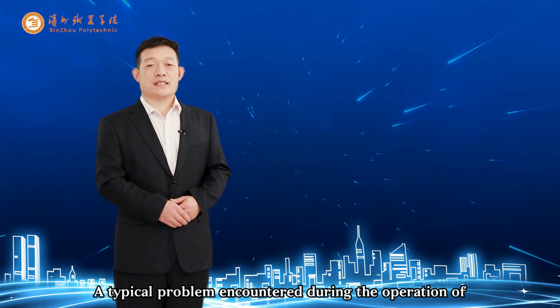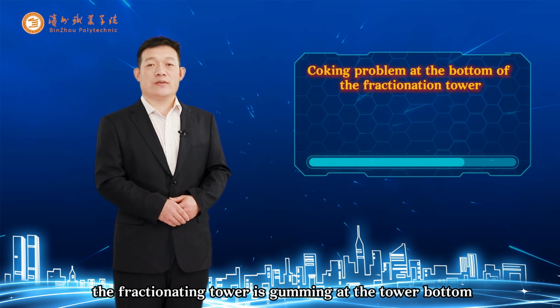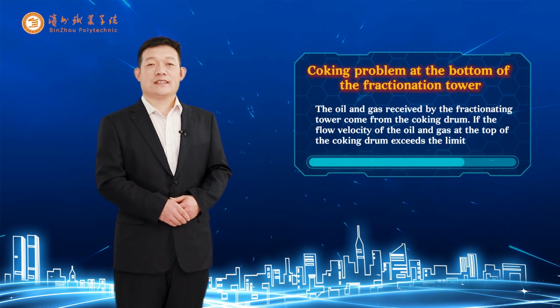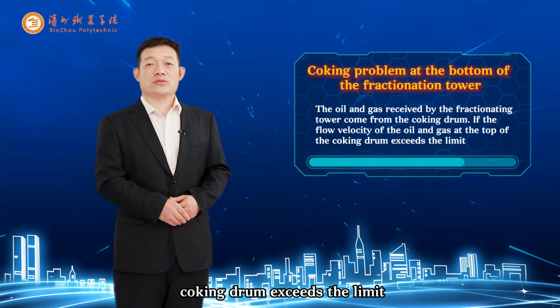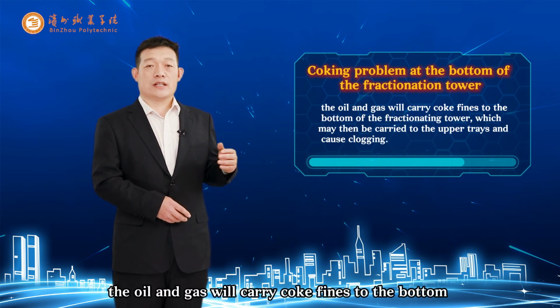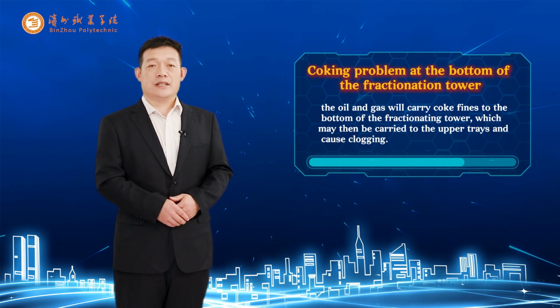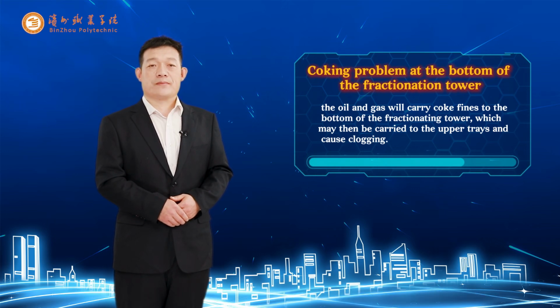A typical problem encountered during the operation of the fractionating tower is gumming at the tower bottom. The oil and gas received by the fractionating tower come from the coking drum. If the flow velocity of the oil and gas at the top of the coking drum exceeds the limit, the oil and gas will carry coke fines to the bottom of the fractionating tower, which may then be carried to the upper trays and cause clogging.